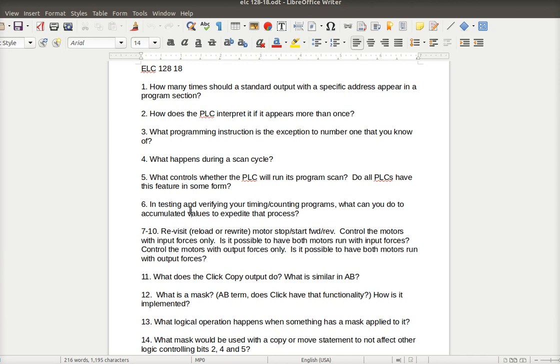That's a good thing to remember in terms of getting programs to step logically, is if you just change an accumulated value in a timer or a counter, that's a little less intrusive than trying to go in and force logic to do something. And it's something you can do without a force, without anything, and you just write it, and the PLC just pretends like, okay, I'm here now.